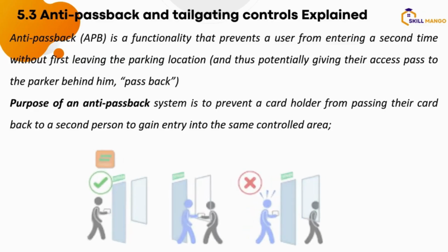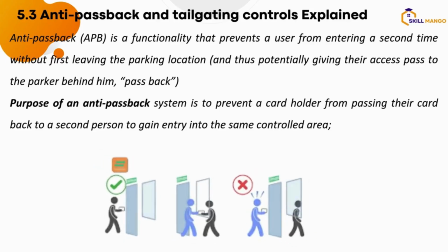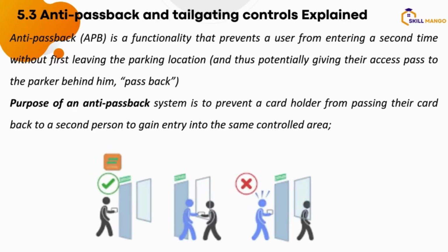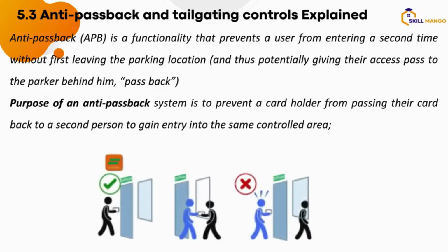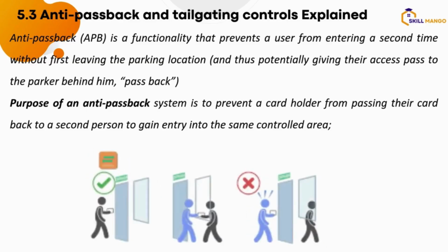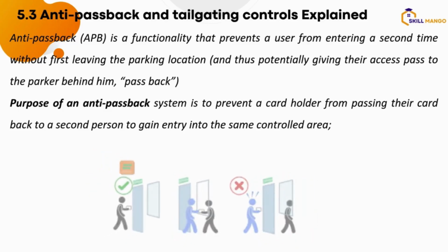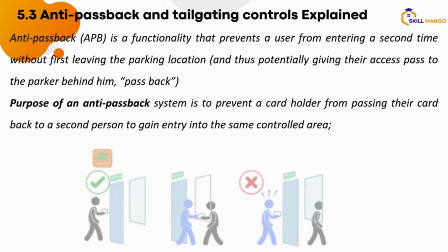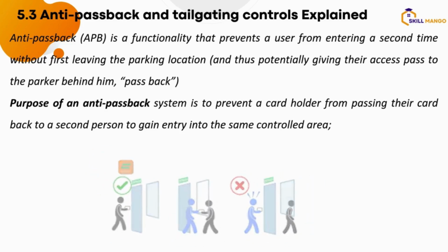Do you understand? It's a very basic setup or configuration. Reader in, reader out, to deploy the anti-passback technology or solution. So your reader in, reader out, then exit button, mag lock at the top of the door, then your power supply, and you do your connection, which I'm going to do practically for you to understand. You follow your color coding, cables, and stuff like that.